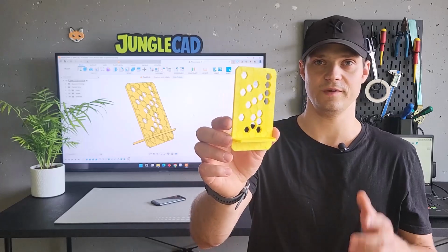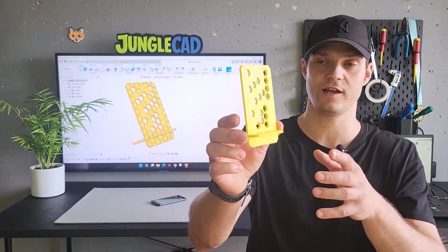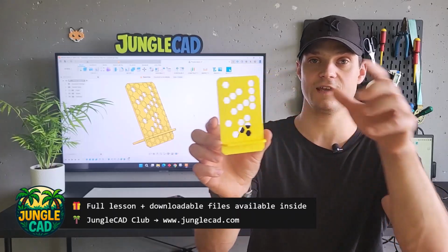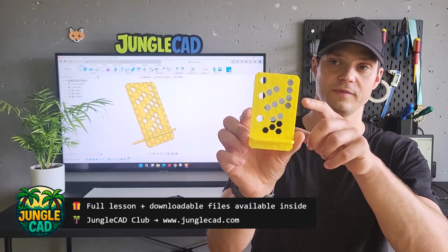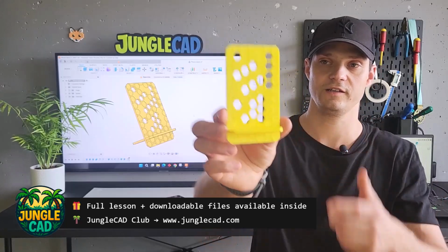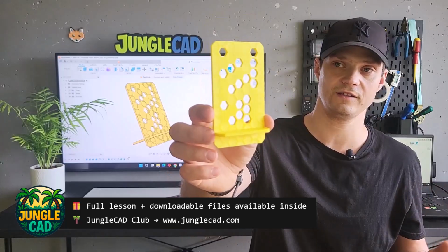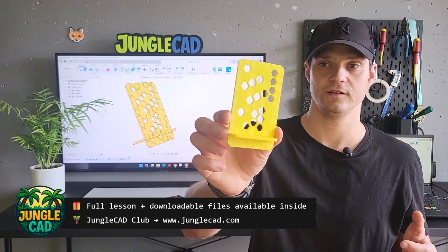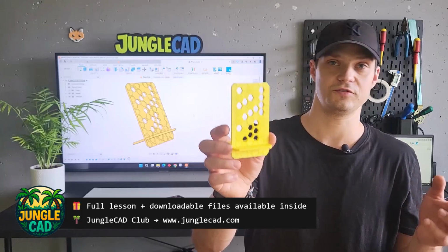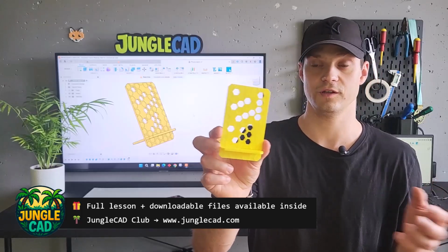In this project we'll be designing this phone stand, and the goal here is to learn how to apply a custom pattern. So for example, here I have different cutouts as honeycomb cells, and it's achieved by applying a pattern feature, and using this tool you can also apply a different pattern. You can have squares, triangles, circles, whatever you want.